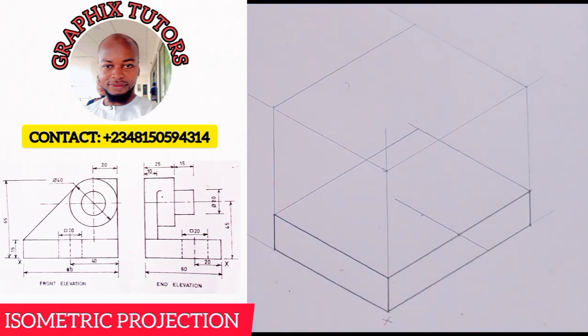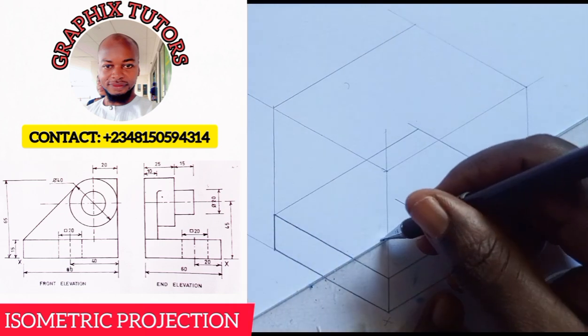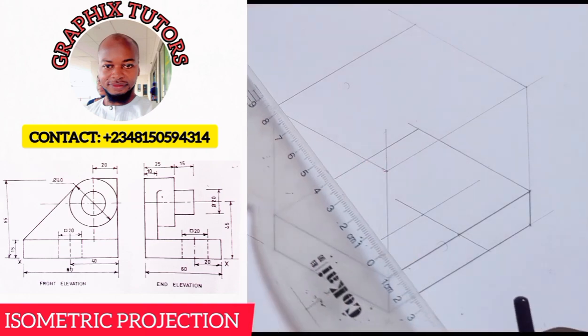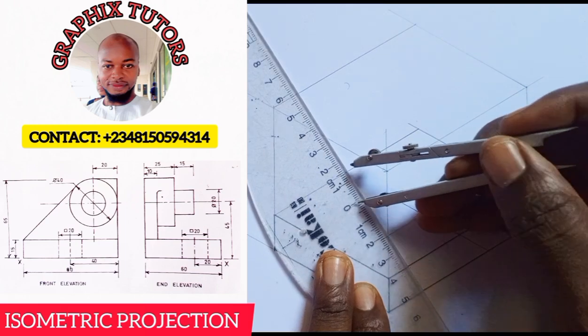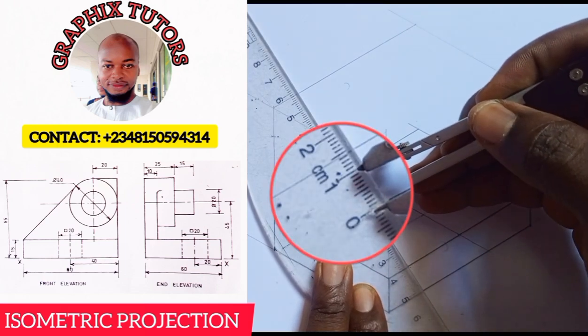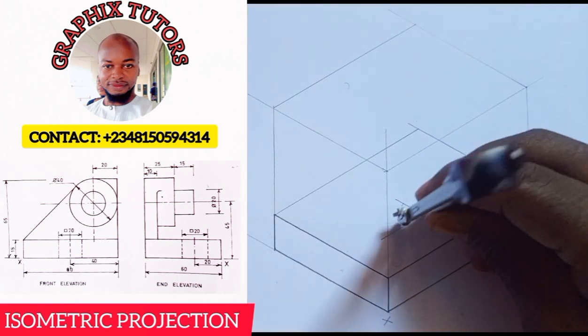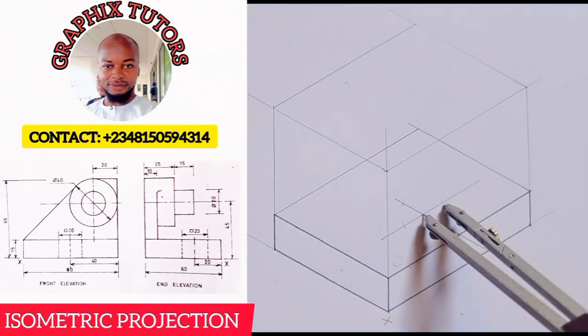So that center you see is the center of my hole this way. Now the question is the diameter, the width and the length of the hole is 20 because it is square in shape. So I'll just take my instrument and I am going to measure 10 each, 10 millimeter. Can you see that? Which I am going to place at the center point here, and I'm going to mark 10 here, 10 here, and also I'll mark 10 here and 10 here.